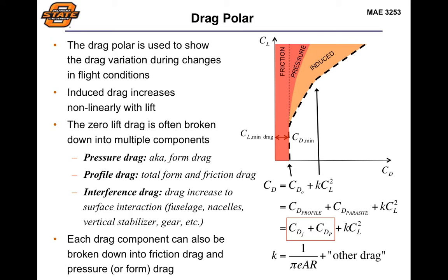So even though for our design concept we're focusing on one overall prediction of these values, they will fluctuate quite a bit, based upon the aircraft operating conditions, speed, altitude, as well as the aircraft operating configurations, such as gear stowed or gear down, flaps stowed or flaps down.